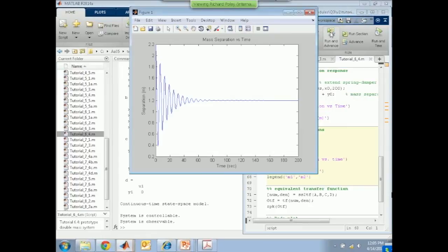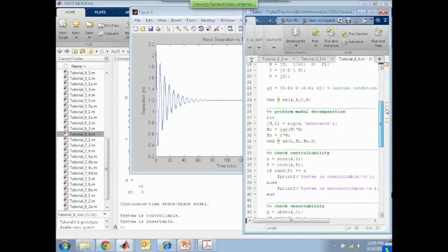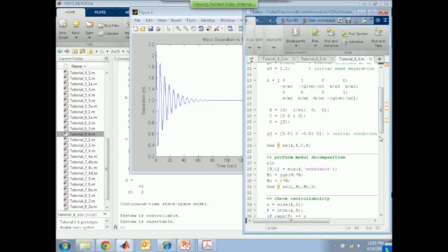And when I run this, you'll see it's a very oscillatory system indeed. Remember, this is seconds now, but you're going to see this come down when we start to control it. And it's very oscillatory, because you're giving it a nudge, and it's going boing, boing, boing, boing, like that. This is the initial condition response. Let me just run back a second and show you what initial condition I've used. This vector here, where I've got the first position mass is a little bit to the right, positive direction to the right, and the second one is a little bit to the left. So I've compressed the spring a little bit, like that, and just let it go. And so this boing, boing thing, it's compressed 10 centimeters or something like that. It's got all that motion, and that's why.